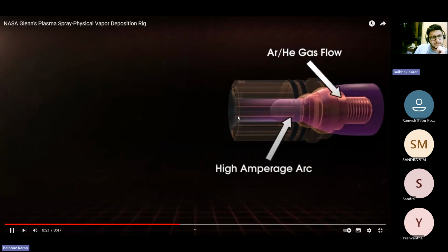electric arc formed between. As I said, there is a helium or argon gas flow in the chamber. Why is it required? You would say, okay, you said that there should be vacuum. Then why are you again saying that there should be an argon and helium gas flow in the chamber? This is to avoid the porosity I discussed earlier.